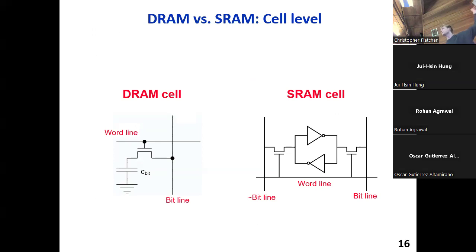Here's a DRAM cell. We have a word line, we have a bit line, we have an access transistor, which is an NMOS, we have a capacitor. We've talked about how, when you organize it into larger hierarchies and choose how you're going to do write back and refresh and pre-charge, this really enables high density, maybe at the cost of access latency. SRAM is the exact opposite.